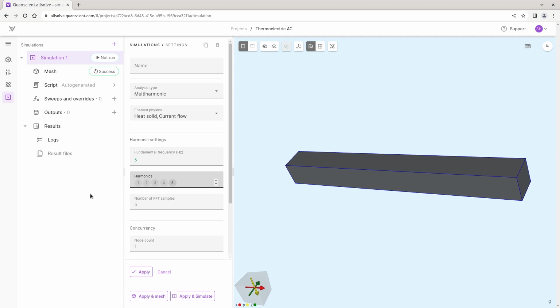Now, in this case, we have a sine 2 pi ft drive of 1 amp. So electrically, we will have here only the harmonic 2. But thermally, due to the Joule heating, J times E, so sine square, we'll have a sine square. Sine square is a constant component, so that is harmonic 1, plus a cosine at double the driving frequency, which